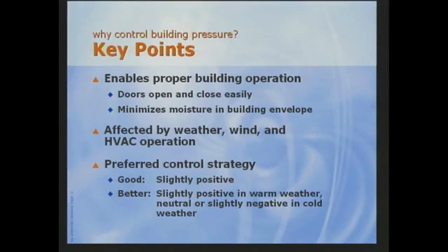Okay, it was important to get everyone on the same sheet there with regards to building pressurization influences. Let's take a moment to summarize. First, if building pressure is not controlled, the physical force of the indoor to outdoor pressure difference can interfere with door operation. Second, unplanned airflow that results from this pressure difference can lead to discomfort, or worse, condensation and damage to the building itself. Both excessively positive or excessively negative pressure can lead to problems.